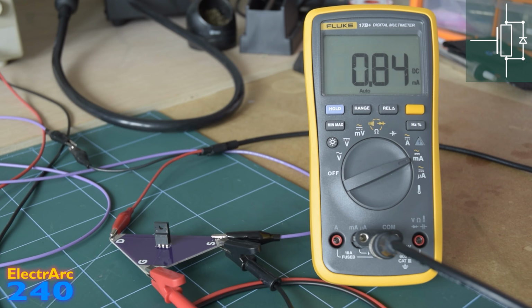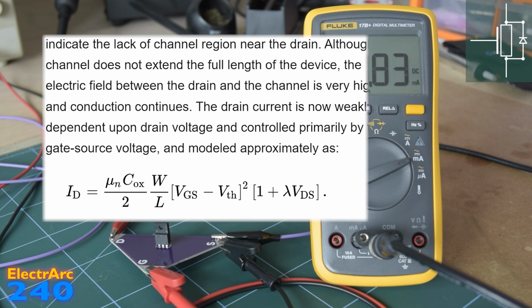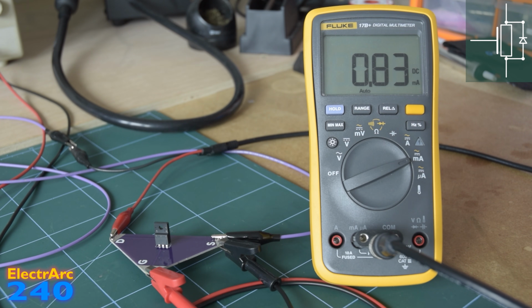Now, there are many analog applications that actually use this saturation region, and some very clever people in the past came up with some lovely equations to approximate this saturation current for any MOSFET and any gate source voltage. However, for power electronics, we do not want any saturation, so we won't be looking at this any further.